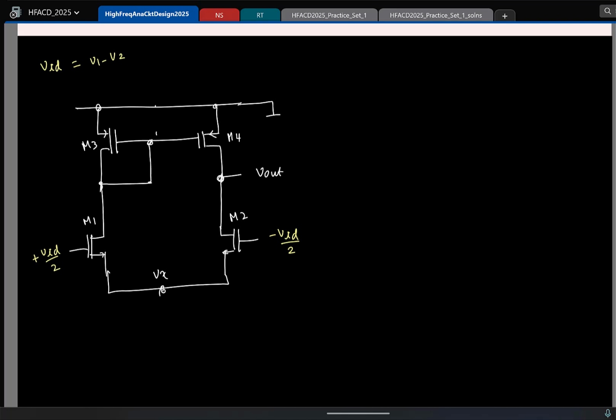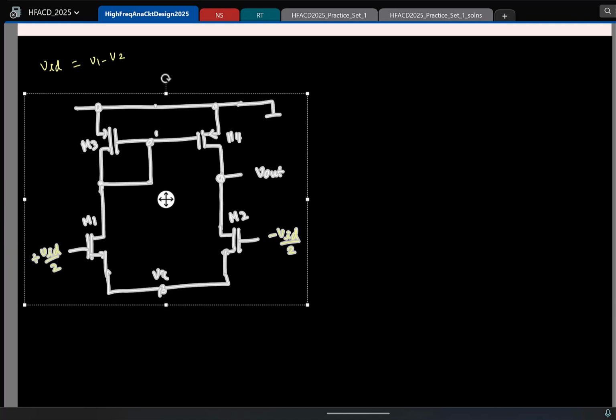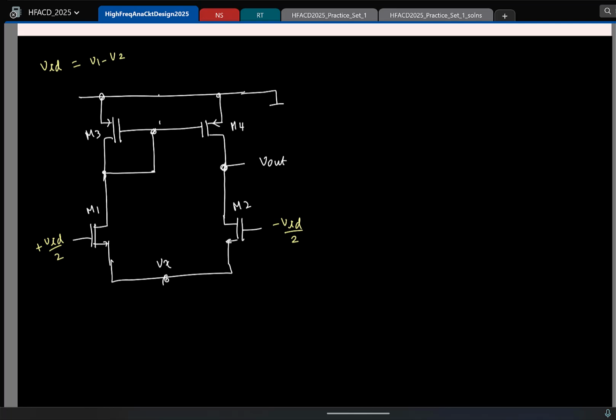But think of it like this. Let us say I now ignore the R0 for the NMOS transistors. I am ignoring Rx for now. Even if there was a resistance Rx, if this was symmetric, that node will still be 0. That is completely from symmetry and linearity, and the fact that you are applying anti-symmetric inputs like this. For now, we will not include Rx because we already have one issue. You don't need to include too many problems at the same time.